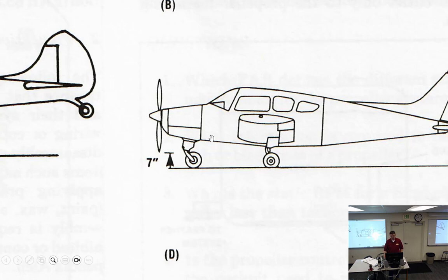What is critical tire blown? It's whichever tire is going to be the worst case scenario. So if this nose wheel blows and the strut deflates, as long as it doesn't hit the ground, it's okay. So with all the mechanical linkage, yeah, depressed.